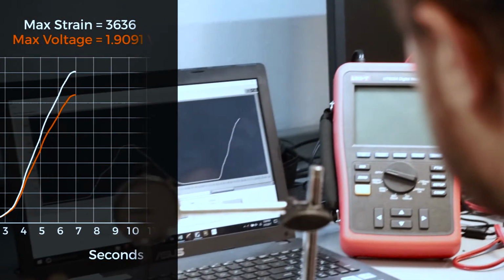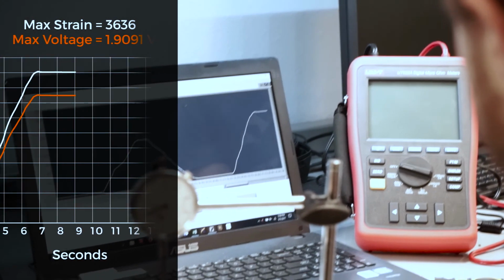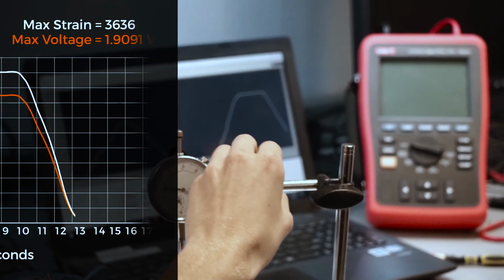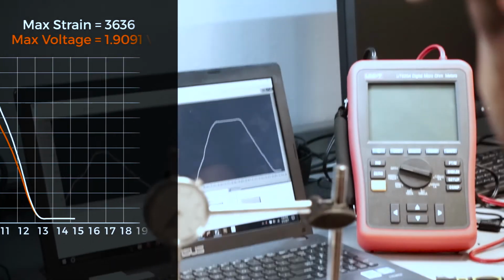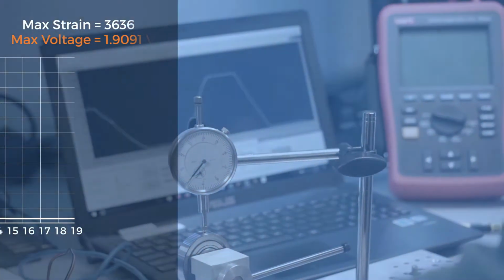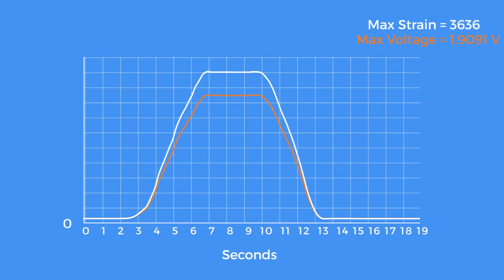As you can see in the graph of our recorded data, the strain varied linearly with the deflection of the beam. Separate trials of different deflection amounts, speeds, and consistencies all yielded similar direct correlation results. This indicates that our results verify the strain gauge's long-standing use as an effective way of measuring strain.